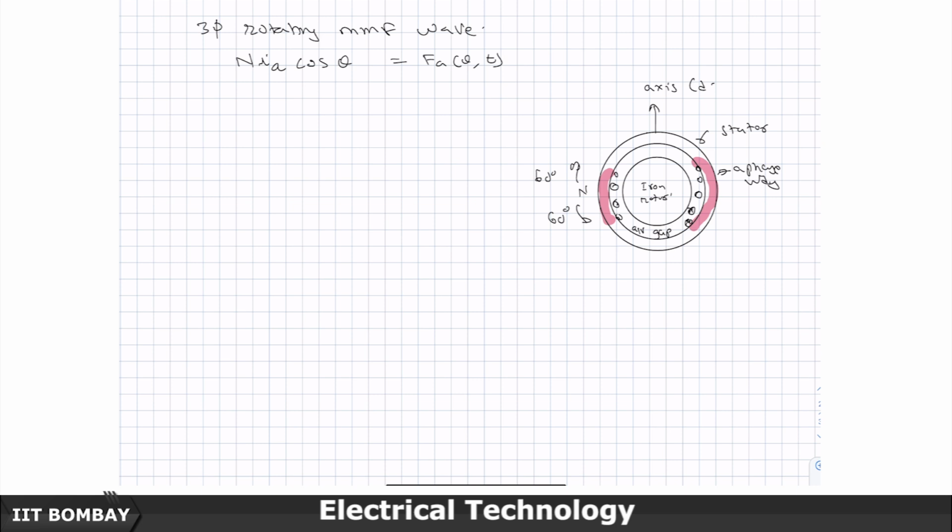So here that stepped waveform, periodic stepped waveform, which is in that 360 degrees, 720 degrees, another 360 degrees you add to it, and it creates a periodic waveform in space. This is the MMF wave, f(θ + 2πn). If you do, it is again the same as f(θ). So, the MMF waveform is periodic in space. This is my definition of periodicity, that the number of revolutions that I keep doing, I will come back to the same waveform.